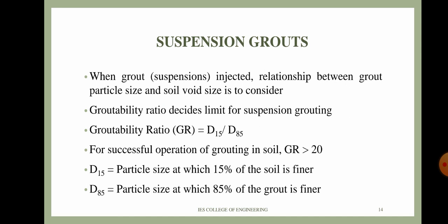Discussing suspension grouts briefly. When grout, that is suspension, is injected, the relationship between grout particle size and soil void size is to be considered very effectively. A groutability ratio has been defined as a rough guide for the suspension grout, and this criterion decides the limit for suspension grouting.